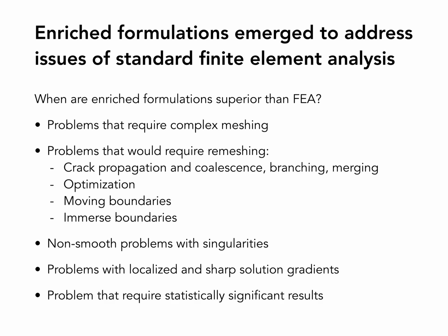And then if you think about the amount of work needed with the standard finite element method to create what we call a matching mesh for every single simulation, it is too much work. So why not just use a single mesh and let the formulation take care of the different placement of the particles? Then you can run 1,000 of these realizations with the same finite element mesh. That is also the power of these enriched finite element methods. Okay.